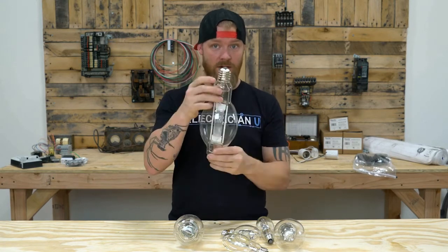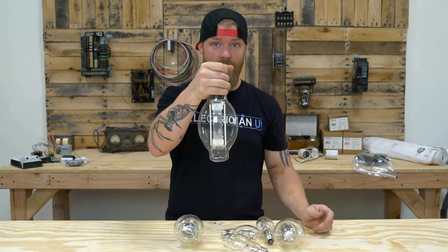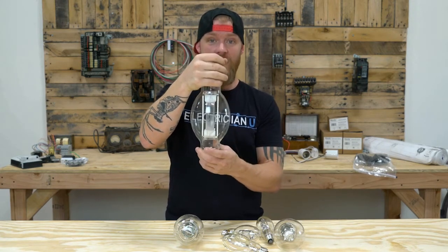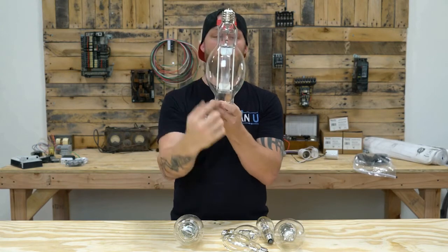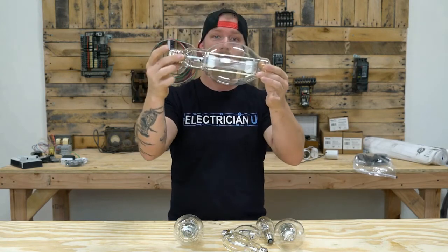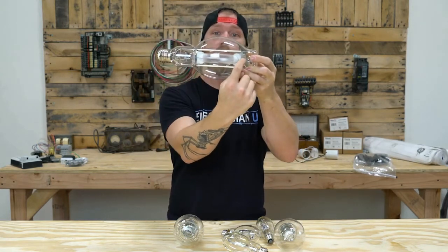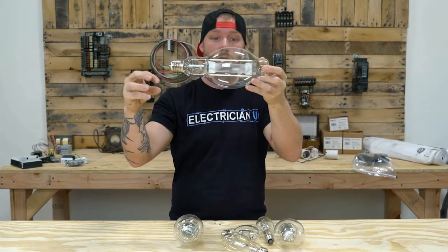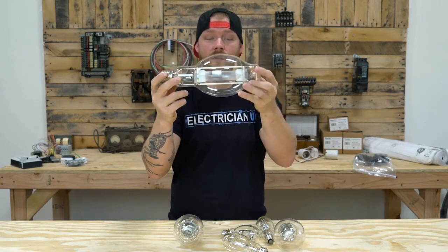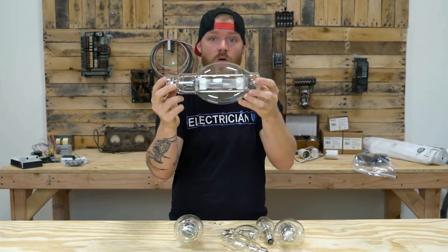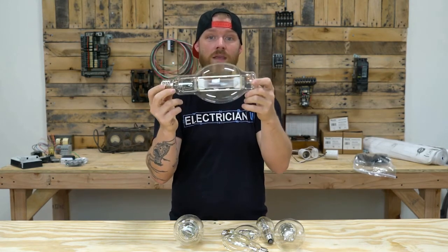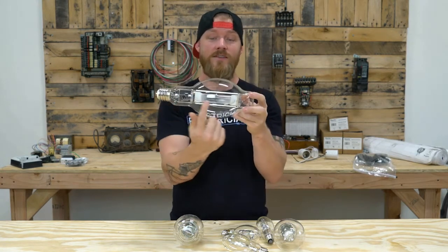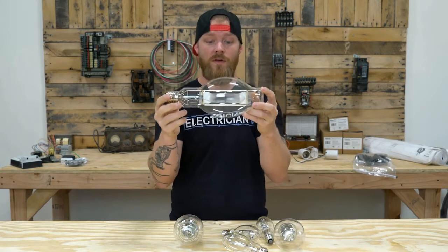There are some lamps meant for mounting upside down or base up. The reason is that if you strike an arc in there and you were to turn the lamp sideways, the arc would dip because of gravity. It's going to dip in the middle and arc against the side of that inner quartz tube, and it's going to heat that quartz tube up to a point where it weakens it, and eventually it's going to burn out or have an explosive death. A lot of these tubes get so hot that they will blow up.